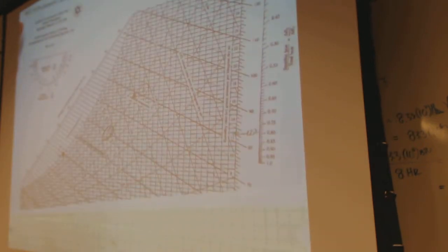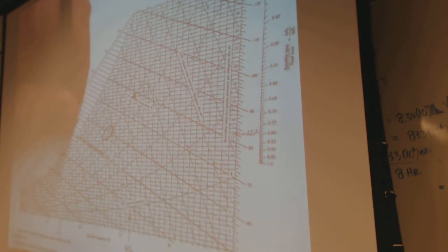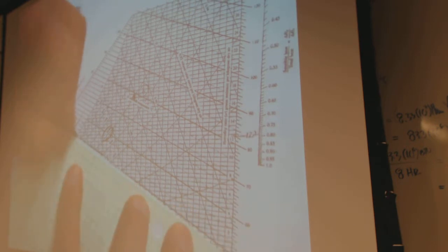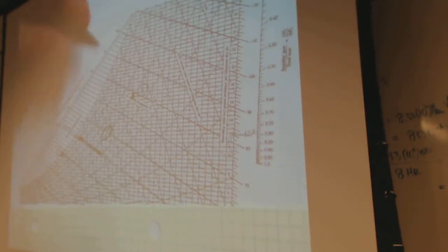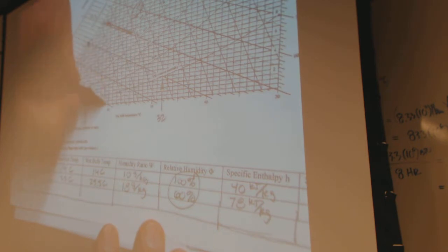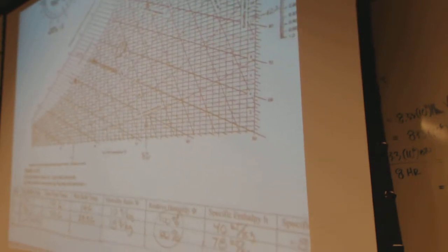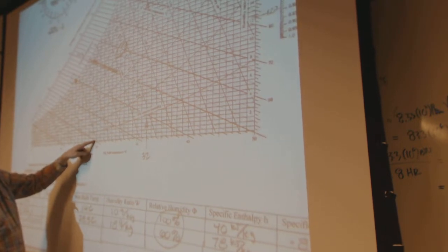So I'm going halfway between two marks there. Calling it 12.2 and 50.3. So the 50.3 line's going this way. 12.2 line somewhere in there, and they intersect right about there. And now I know I can fill in the rest of my state. Tells me the outlet's going to be at about 19.5 perhaps. Come down here, it's less than 20. 19.4 based on where I drew it.